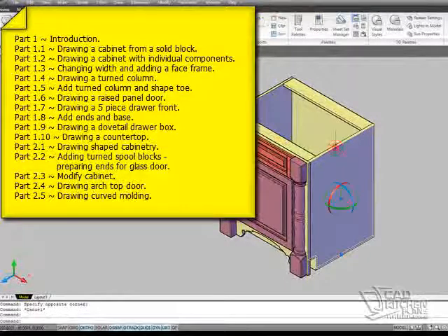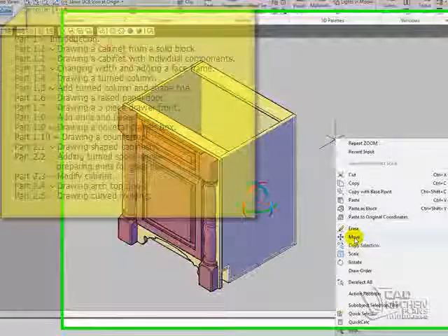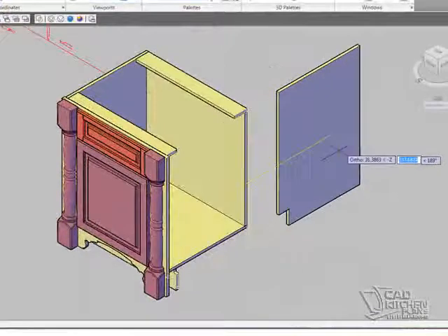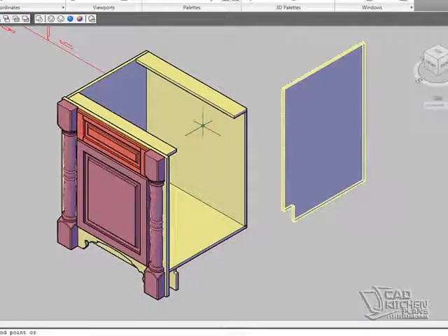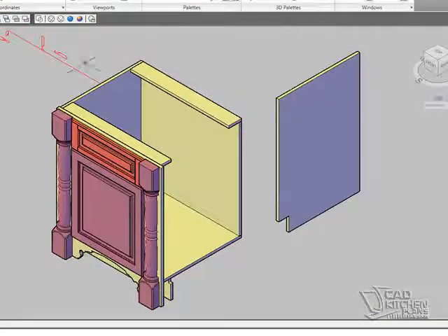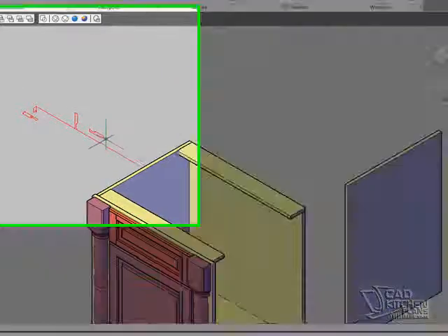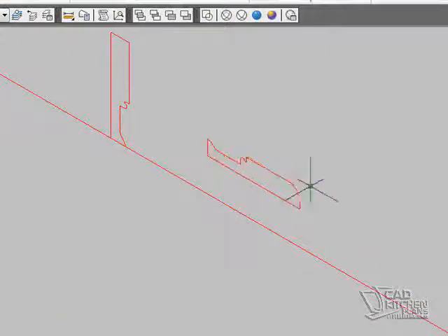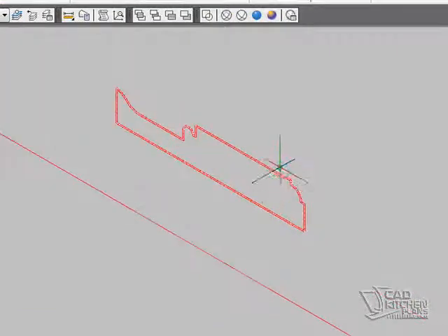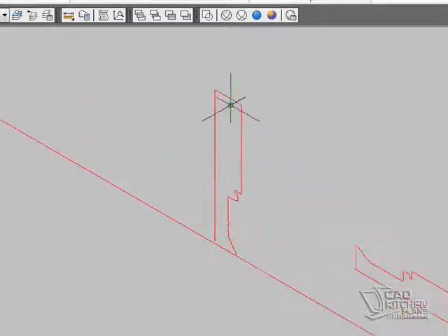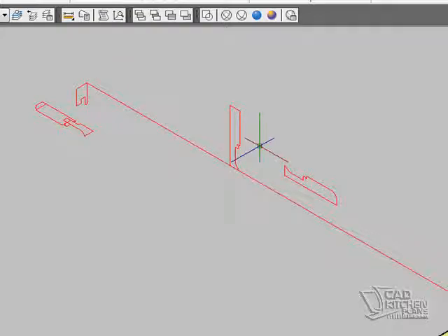I'm going to use what they call an integral panel end, and what that is actually where the raised panel becomes the end of the cabinet. So I've taken our profile that I worked with here for the door, which is down here, and this is the perimeter profile that I used for that door, and I've modified it. You can see there, this outside bead right here, I have removed it from this profile, which I'm going to use for the integral panel end.